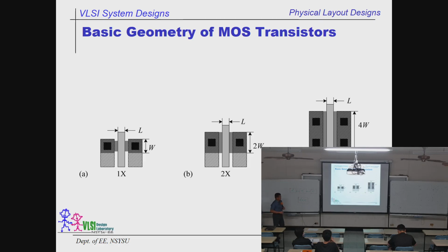All right. So right now, let's talk about the size. Not only do we need a minimal size, what if we need a bigger size? Okay, it's a single W. Now with a bigger, fatter transistor, this is 4 times the width, 4 times larger. The larger your width, remember what I said before, the more contacts you need to add over there, because you cannot use a big hole, because the contact is exact. You cannot change the size.